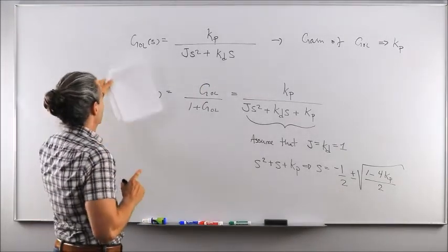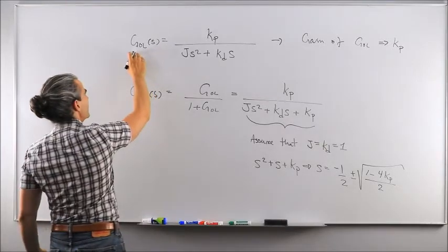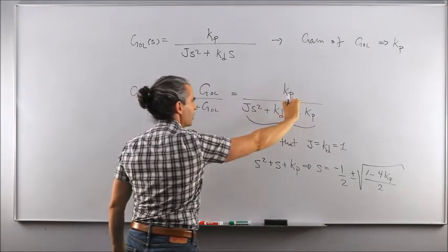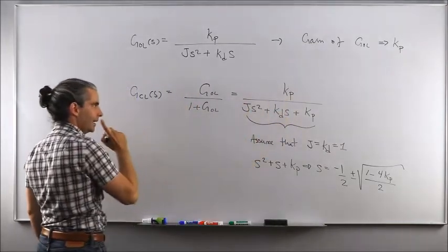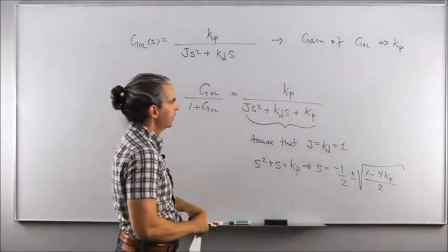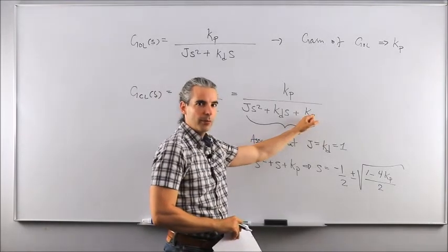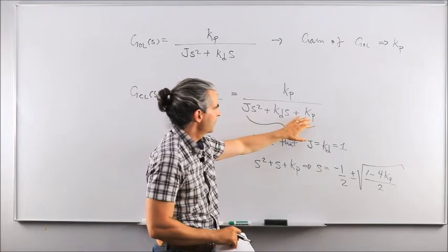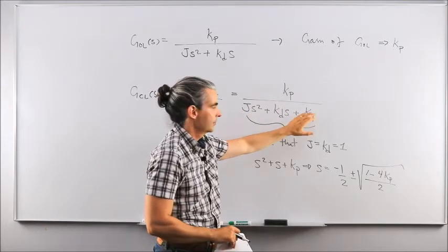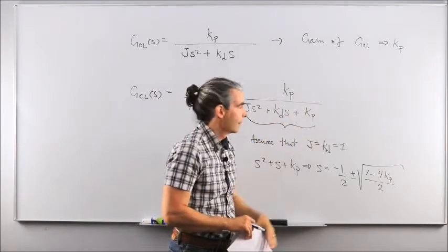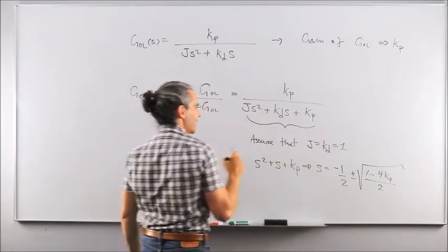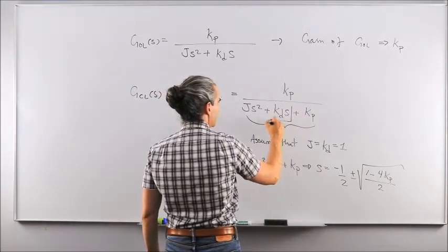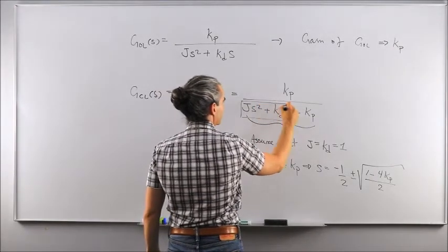And how does that relate to this? Well, that is because if we have a map of the closed loop poles in a complex plane, and if we were to set Kp equal to 0, because remember, the root locus is a map of the closed loop poles whenever Kp ranges from 0 to infinity, then whenever Kp is exactly equal to 0, you get this characteristic equation.